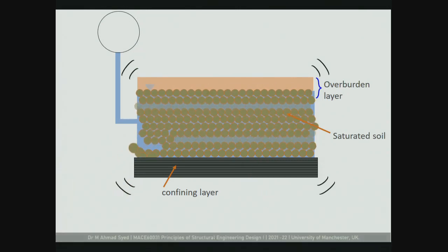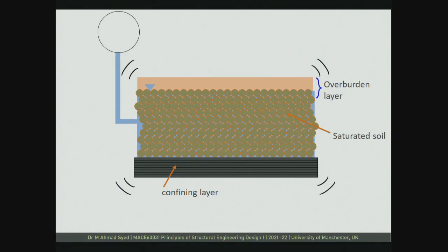But after some time, it will transition back to another equilibrium where you have a relatively denser configuration of individual grains, and the pore water pressure will dissipate. But liquefaction has already occurred. Now, during that time, when liquefaction was occurring, imagine that if you had a structure on top of it, it will not be able to withstand the forces, it will just collapse. So after some time, it will transition back to hydrostatic pressure.